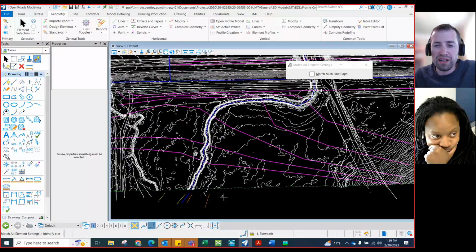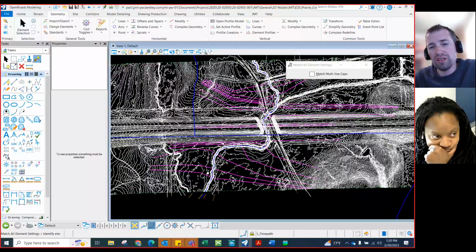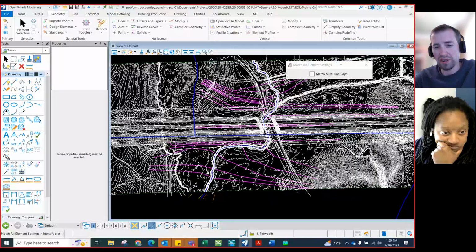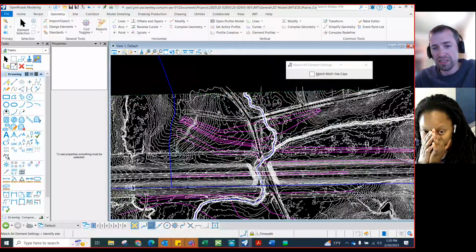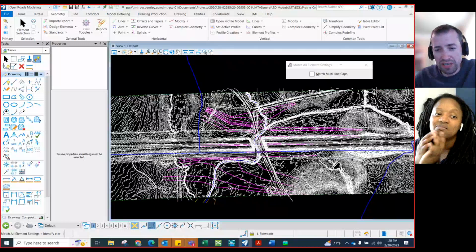So if I didn't emphasize it enough, HEC-RAS, I don't think I mentioned this yet, but I will be reiterating this over and over. In HEC-RAS, you consider your directions looking downstream. So we drew that in going upstream, but as far as what's left and what's right, I'm always going to imagine myself looking downstream on this channel.